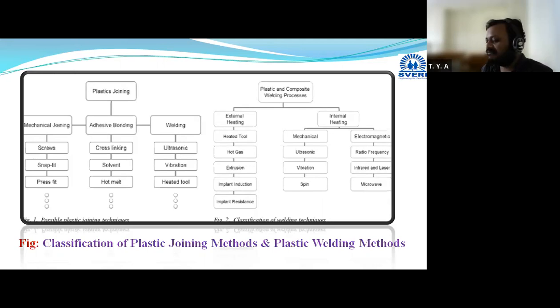What we are doing is taking the raw material for our workpiece and winding a coil, and electric current is passed through that coil. As we pass the electric current through that coil, it will generate a magnetic field. Due to that magnetic field, eddy currents are generated, and those eddy currents will heat the workpiece. Direct heating we are not doing here. So these are the mediums.